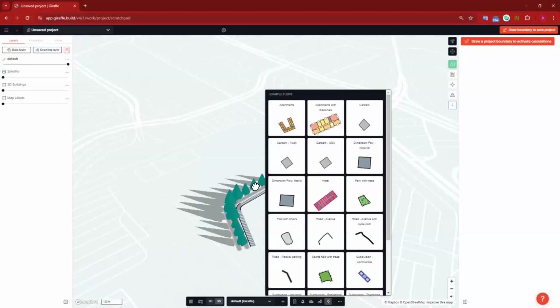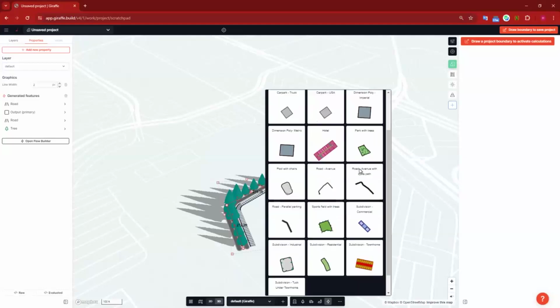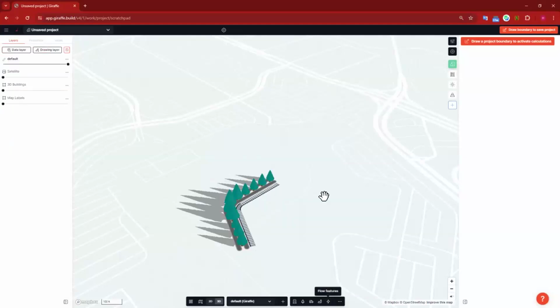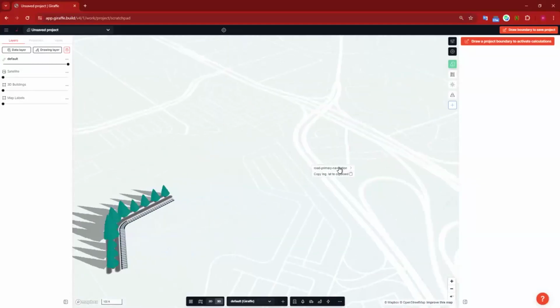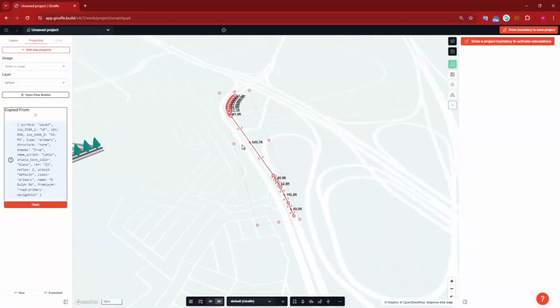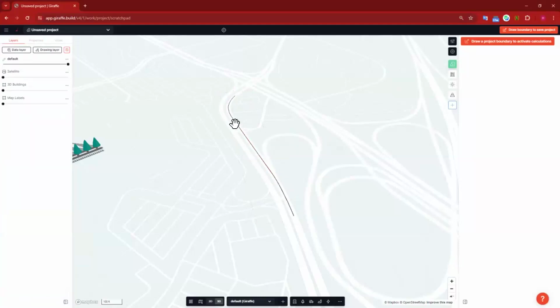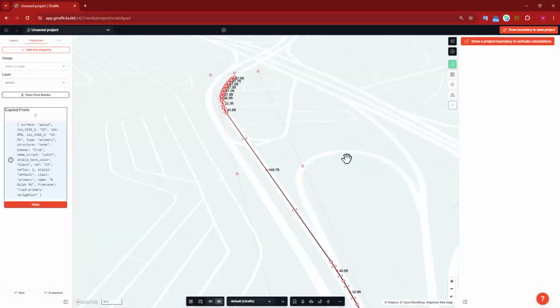But you'll note that these flows that you create in your project don't show up in the lightning bolt here. So how can I reuse this? I might want to apply this boulevard to all of my roads in my project. Well, luckily, you can now using the eyedropper command.